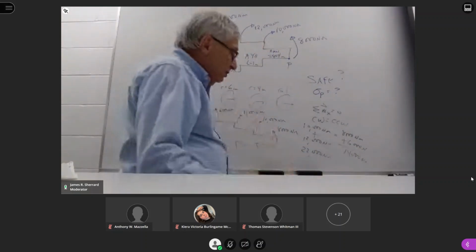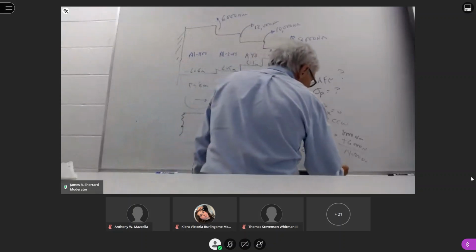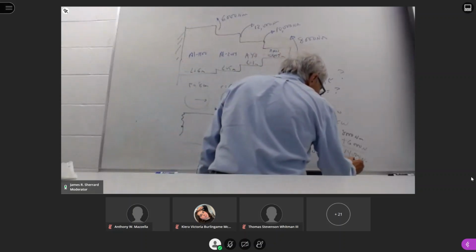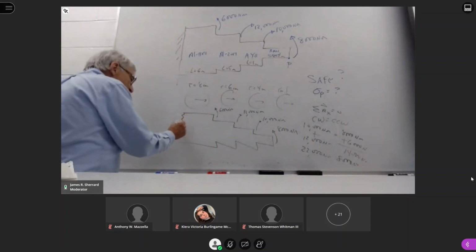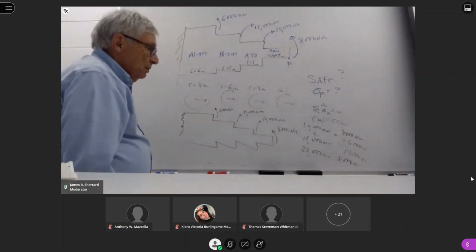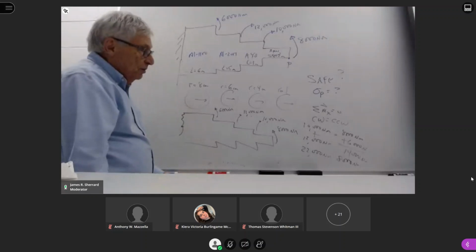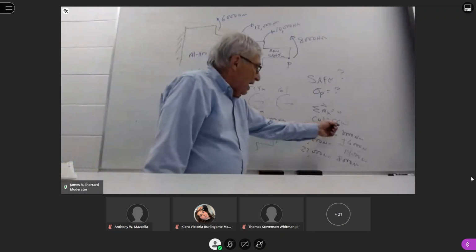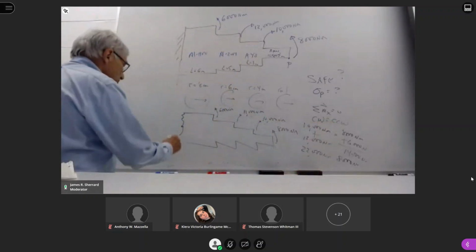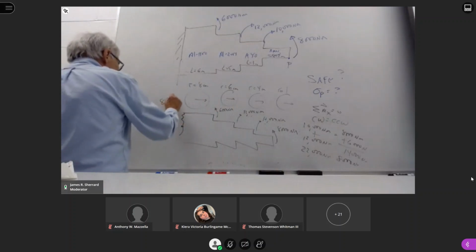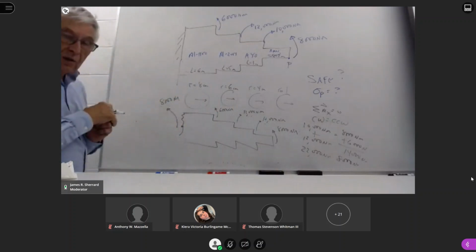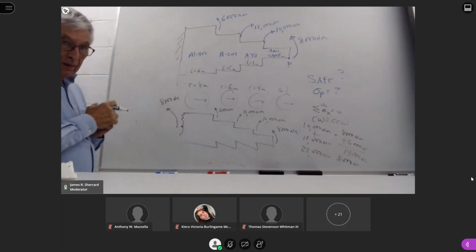So that means the difference between the two, which is going to be 8,000 Newton meters, we have to add at the attachment point, because that's the only place we can add forces, moments, torques, couples. It has to be counterclockwise in nature. So that is a complete free body diagram.